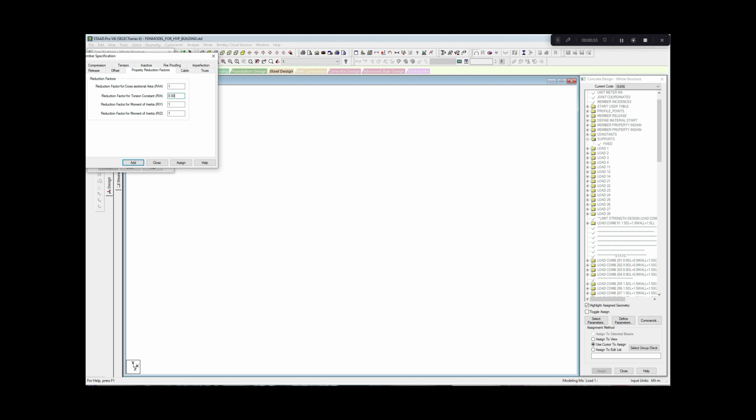if equilibrium can be sustained. So if we reduce the torsion to 0, there could be numerical instability. So we shall make this torsional constant 0.00, along the centroidal axis. Then along the major axis, the beam shall have 35%, so in both major and minor direction 35%, so 0.35 assigned.